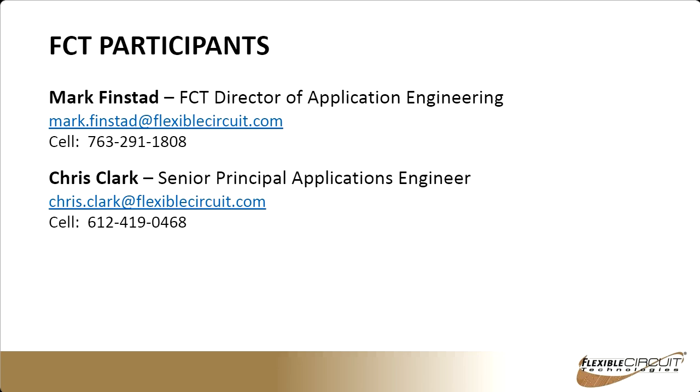Next one is, what advancements are being made in flexible heater technology? I don't know about you, Mark, but for me, I think the biggest thing is probably the operating temperature at which we can produce heaters now. So if you go back a decade or so, typically that was at 125, 130 C. Now with these thermoplastic polyimides, we can get up to 200 C. I mean, do you have any additional thoughts on that?